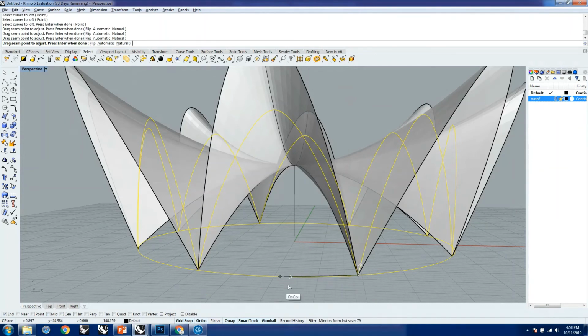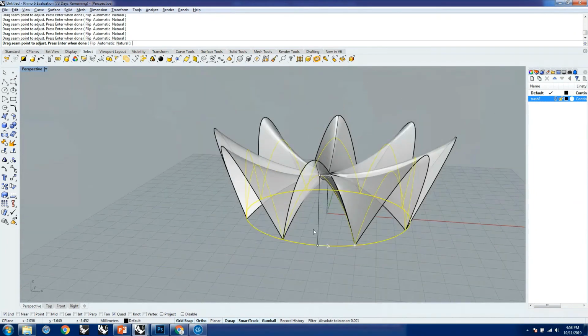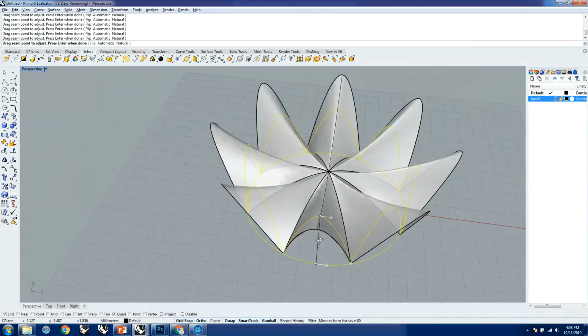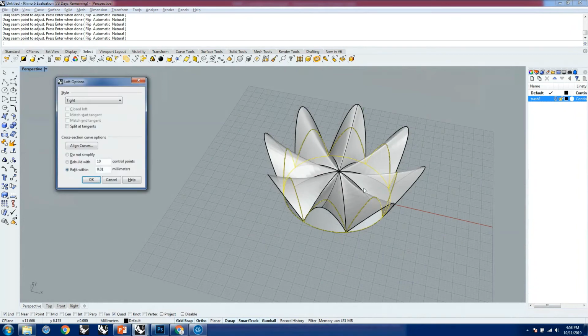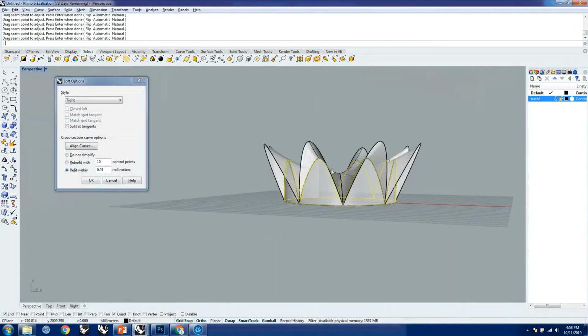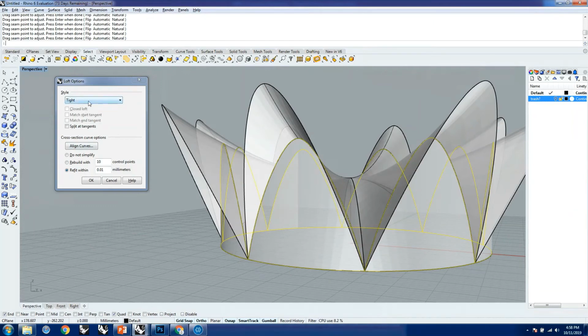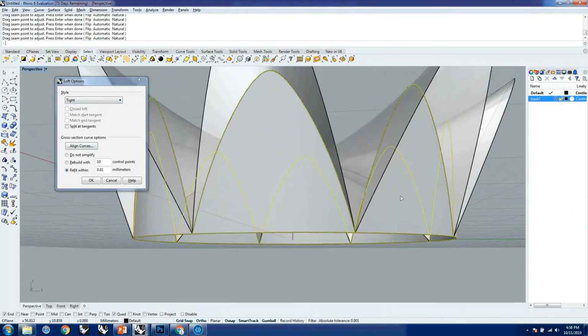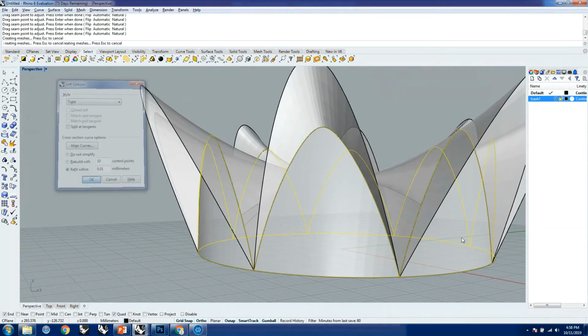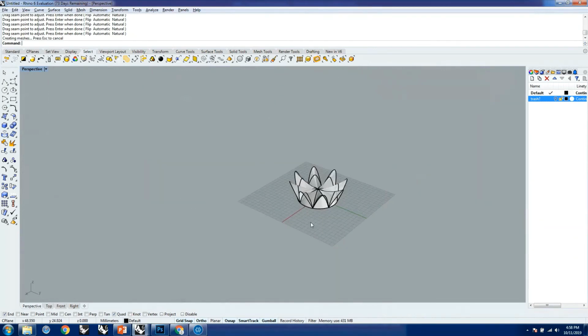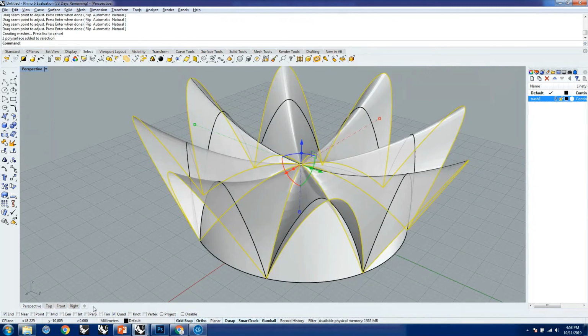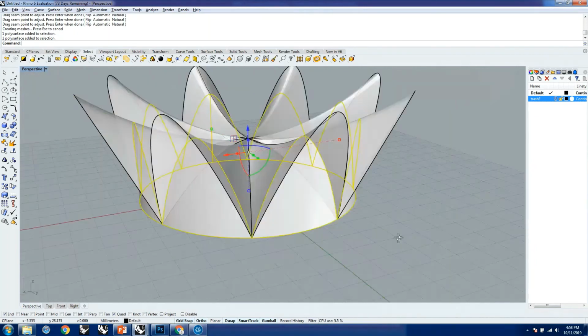So I'm just going to drag the seam, and let's see if the quads can help us. Okay, this is one quad, and the other one should be somewhere here. Okay, yes. So now the seam is clean and it's aligned and everything, and they are in the same direction. So let's go ahead and loft. We're obviously going to use the tight option because that's exactly what we want it to look like. And there we go. There it is. The petals or the roof and the facade.